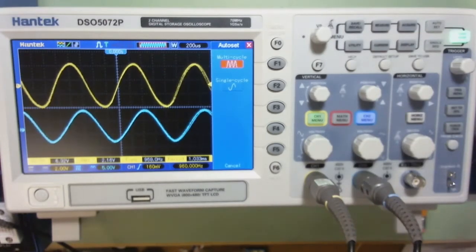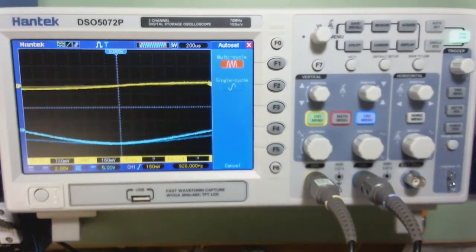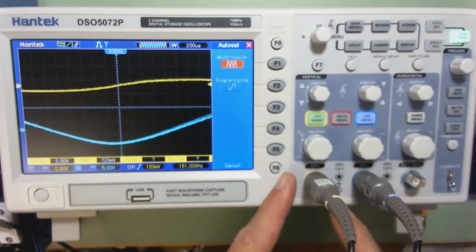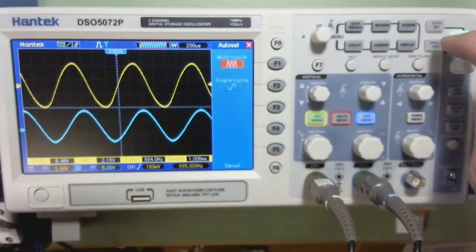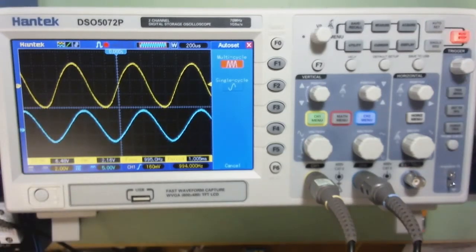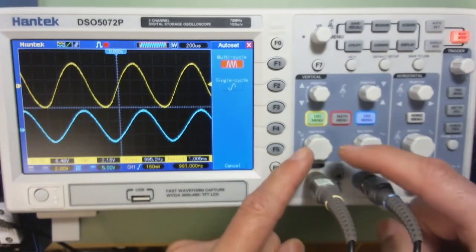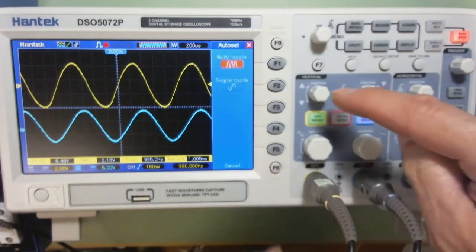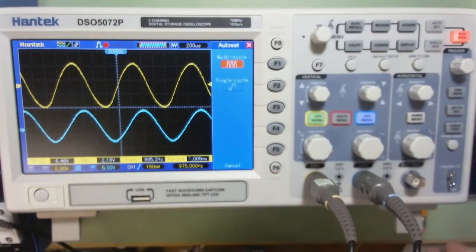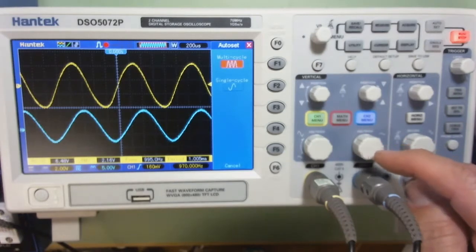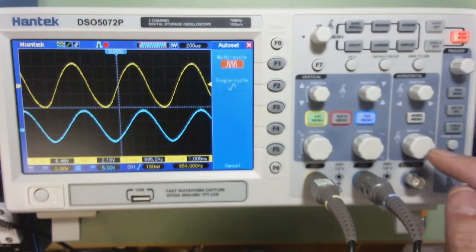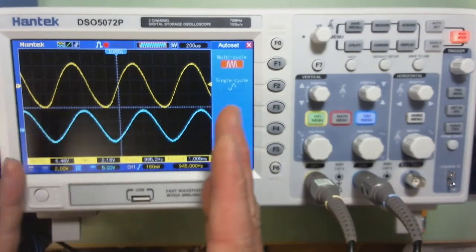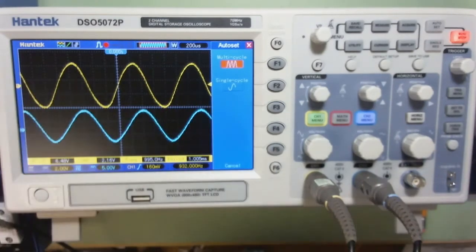So when we walk up to these things, we always have a couple channels. Sometimes scopes have multiple channels, many channels. We'll use some 4-channel scopes next term. But this always controls my magnification in the vertical. Just pause that there. This knob controls my magnification in the vertical and where it's located. And most scopes are laid out like this. This knob controls my magnification on channel 2 in the vertical and where it's located. And then this knob controls how it's spread out on the horizontal, time-wise.